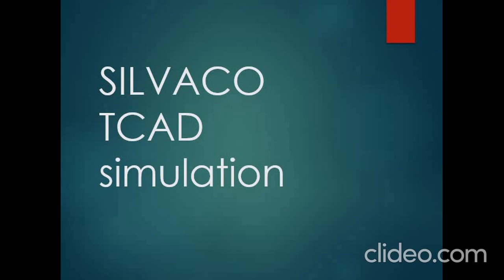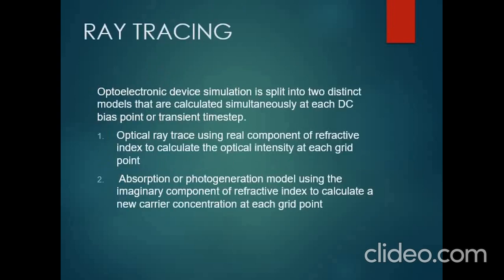So coming to the first slide, ray tracing. It is important to explain this here because it will be important to do simulations in Silvaco. Optoelectronic device simulation is split into two distinct models that are calculated simultaneously at each DC bias point or transient time step. First, optical ray trace using the real component of refractive index to calculate the optical intensity at each grid point. And the second is the absorption and photogeneration model using the imaginary component of refractive index to calculate the new carrier concentration at each grid point. So this is one of the important things. Remember that this is why we need the .nk file here.